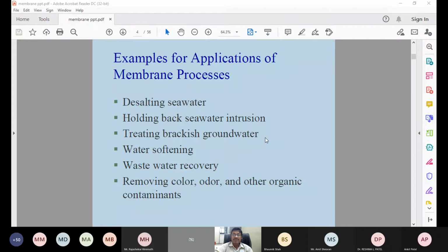If your source of water to your house supply is river water, you don't need RO. Nowadays people are moving towards RO systems, but they are not checking their dissolved solid content. First check your dissolved solid content.